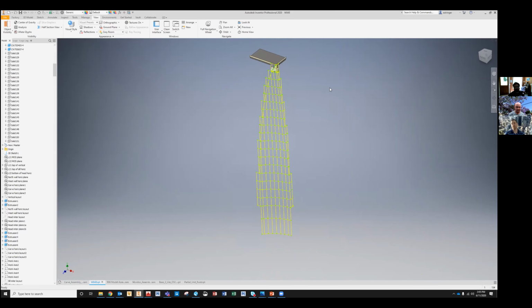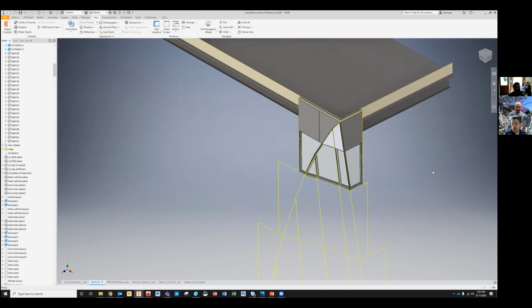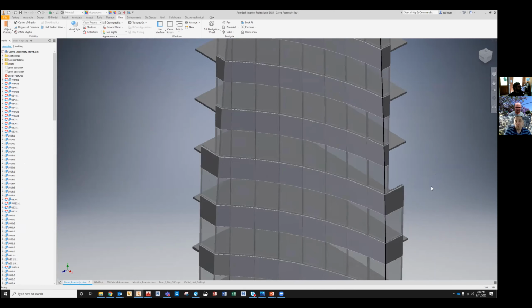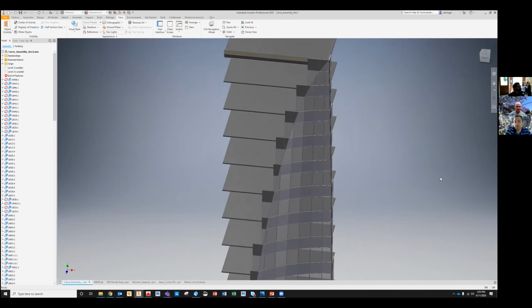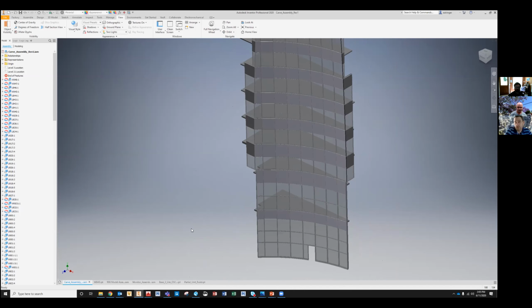And that wireframe was developed in conjunction with the architect. On the corners where the curves come together, their original geometry had a lot of little tiny triangular pieces and things that couldn't be made. So we worked extensively with them to get the geometry optimized to eliminate as much of that as we could. And then the other thing we did at the end for field is we worked with our layout guys to get 3D points for their total station directly out of the model too. Sorry, go ahead, Ed.